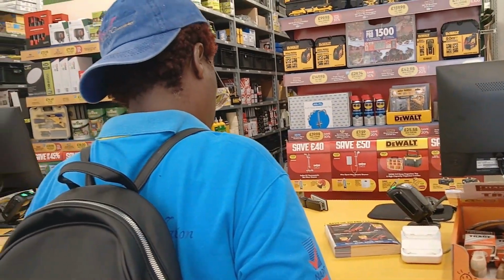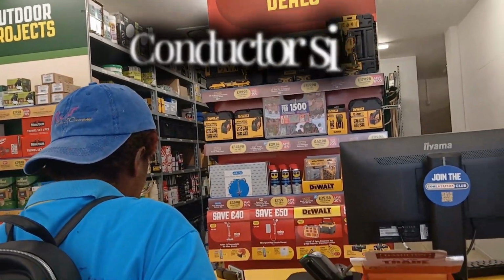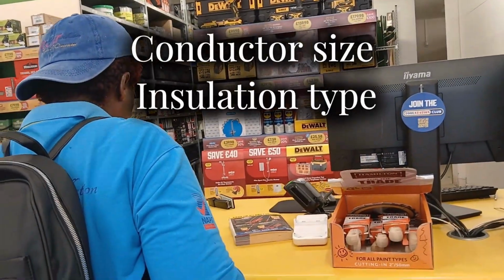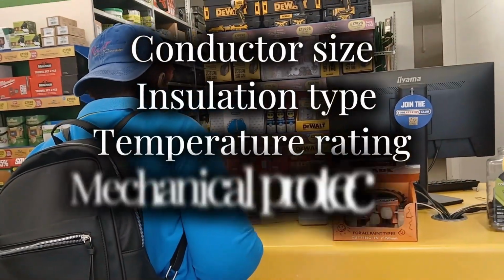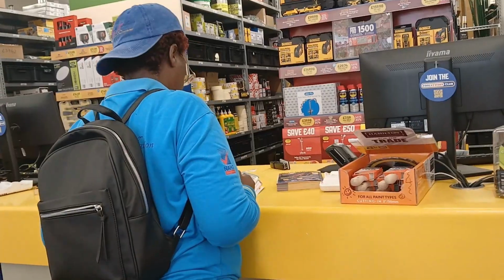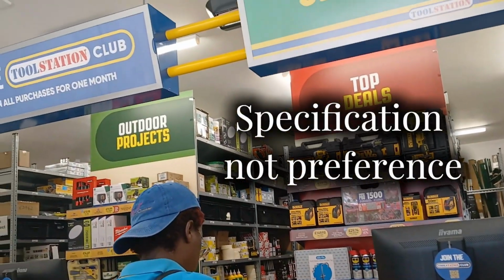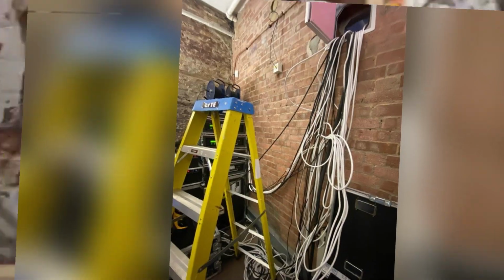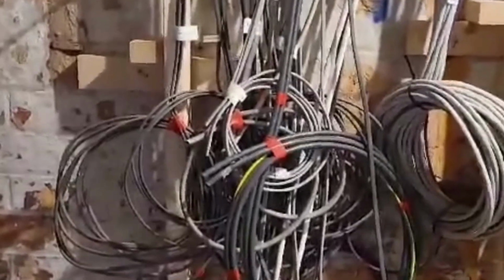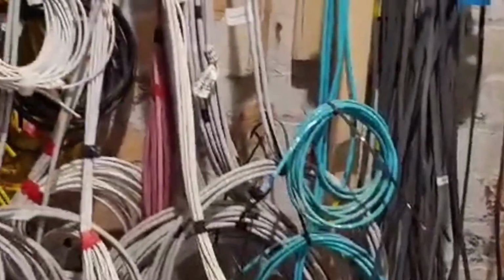So when you go to buy cable, you're not just choosing size, you're choosing conductor size, insulation type, temperature rating, mechanical protection, number of cores. Cable selection is specification, not preference. This is some wiring going on here. We've got everything going on here. We've got data.